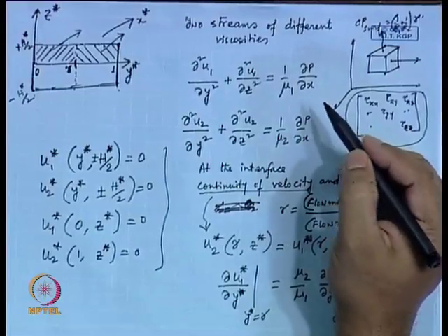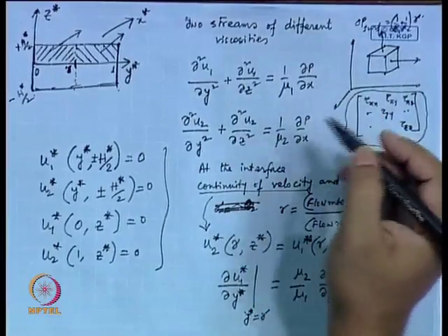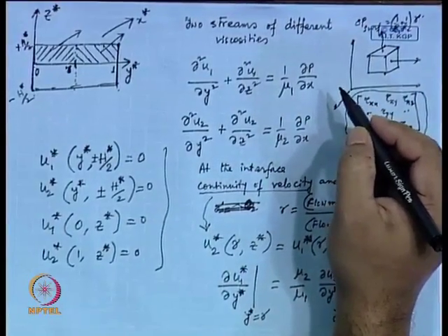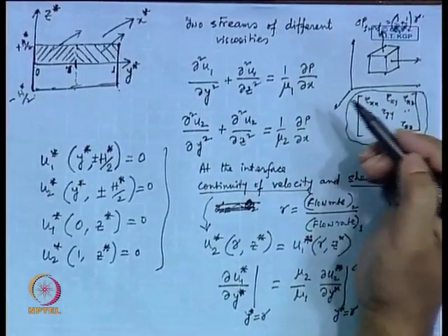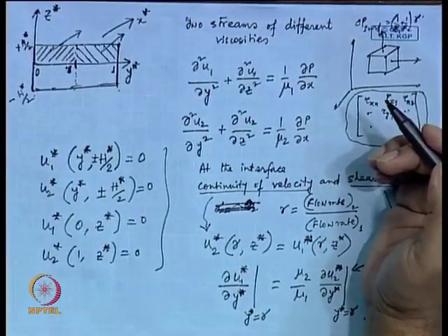However, this is not a complete equation as far as the microscale transport is concerned, because if you look at the Navier-Stokes equation, there is an additional term, which is typically the body force, basically gravity or the Coulomb force. In fact, we will discuss this down the line, something called a zeta potential. There you will have an additional term.